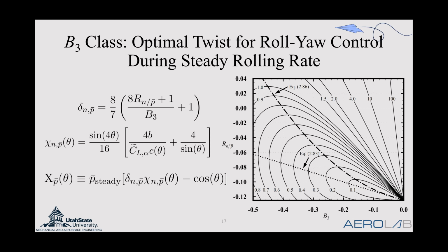You want to use that to accelerate yourself to the right. So you bank the aircraft to the right, but the aircraft naturally wants to yaw to the left. That's adverse yaw. And that's what we're showing here. If you have an elliptic lift distribution and you deflect the ailerons, it doesn't matter where you put those ailerons or how it's designed, you will always get adverse yaw. So the aircraft's going to want to yaw the opposite direction that you're trying to turn. Okay.